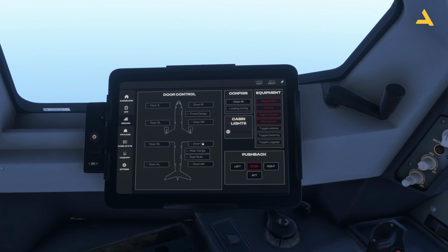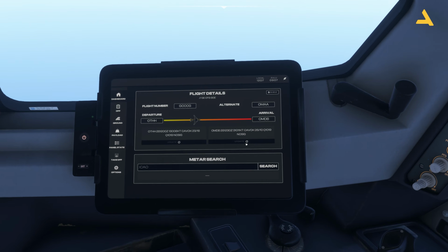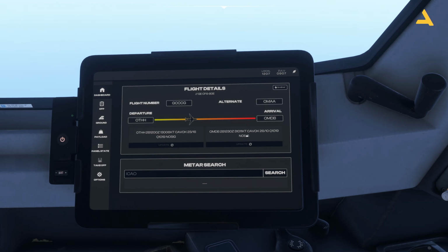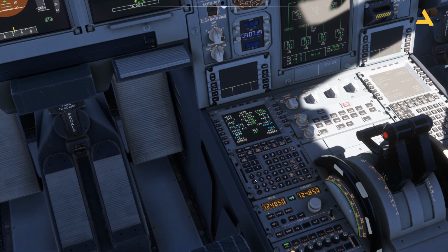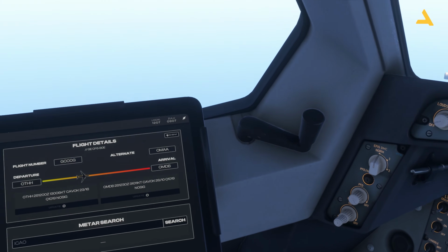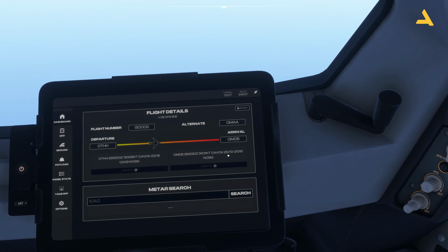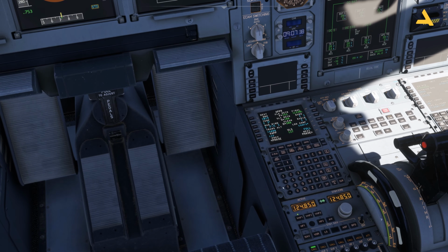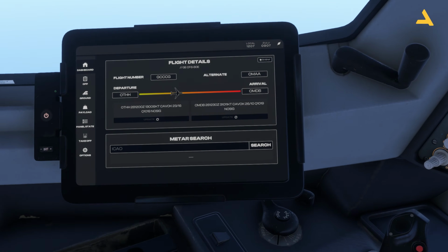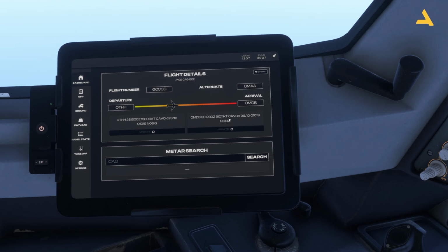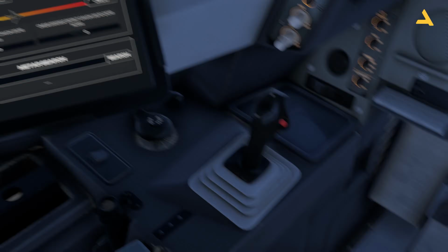So first of all, let's get the QNH. Go to this option, dashboard, and over here, you will see the weather for Dubai, and the QNH is 1019. As you can see, it's over here. So let's enter 1019. Now the temperature for Dubai, it is 26 degrees. Pretty hot nowadays, even in December. And the wind is 310 degrees, 11 knots. This is the direction and this is the speed, 310, 11.